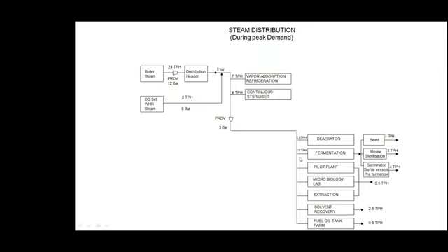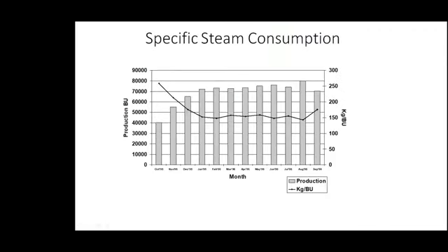Thirdly, make an estimate of how much probably. If you can't calculate, then you can estimate. If you can't estimate, then you can guesstimate. But at least some bad data is better than no data. So you get a rough steam balance showing where all the steam is going. You may not be much away from the actual result. So this gives you an indication where all it is going and where to focus. And also relate it with production.